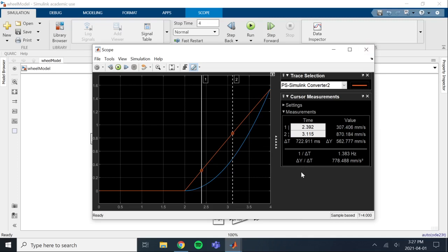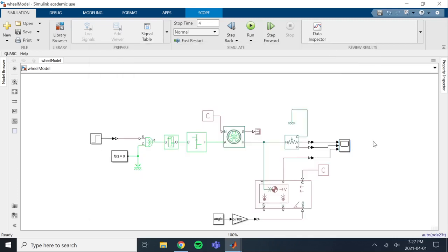If we had some different gear ratios, maybe we'd be going even faster. So if we lowered the gear ratio of our gearbox, it's possible that we could go faster just because our rotation speed wouldn't be reduced, but our torque would also be reduced. So we might actually still be slipping. Okay, so now this is basically our setup for driving the Rover.